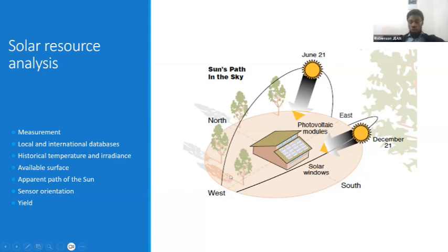For a given season, like June, the sun path is that line, let me show you with the last. The sun path is that line in June, and in winter the sun path is this. So if we could change this value, it would be better. But for the global year, for the maximal captation, it is better to set it equal to the latitude of the place.